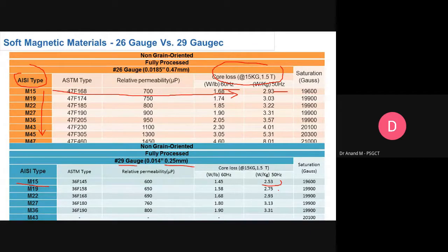In an EV system, the electromagnetic drive system, if you make even a small or incremental change with respect to the lamination material, it will have a beneficial effect in reducing the core loss component of the drive, which means that your efficiency will directly increase, and the torque handling capability and the specific peak power handling capability will all be at an enhanced level. But they may say that the cost of the materials will increase when we go for low core loss, but when the volume goes up, automatically the cost per kg will be reasonable. So this is one factor.